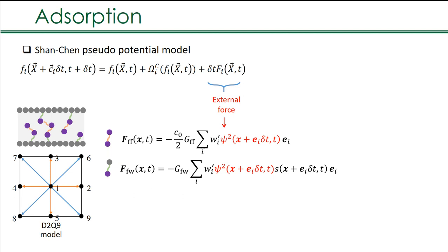You may think of it as effective mass. In this model, fluid particles in the lattice will be subjected to the forces from neighboring lattices, and the neighboring fluid and solid lattices decide the interaction types. And after calculating the interaction forces with the neighboring 8 lattices, we can calculate the resultant force. And the adsorption behavior is represented by this resultant force.